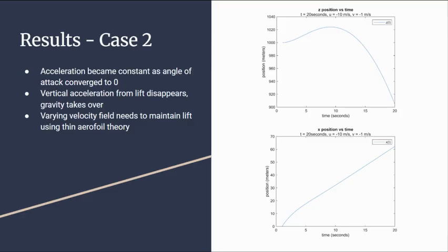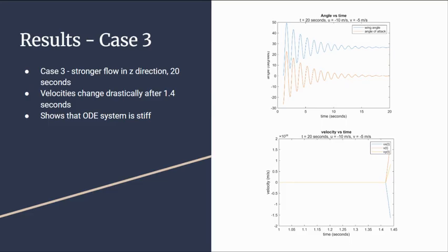In some of the simulations, it increased so rapidly that it effectively went to infinity near the end of the run. This isn't a physical effect, it is a numerical consequence of the model being stiff. RK4 works well for smooth, well-behaved systems, but here it amplifies small oscillations until the solution breaks apart.